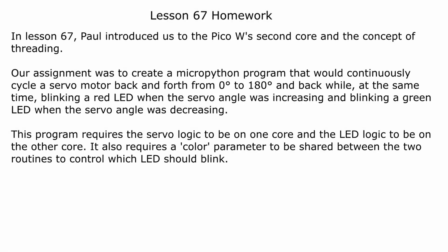In Lesson 67, Paul introduced us to the Pico W's second core and the concept of threading. Our assignment was to create a MicroPython program that would continuously cycle a servo motor back and forth from 0 to 180 degrees and back, while at the same time blinking a red LED when the servo angle was increasing and blinking a green LED when the servo angle was decreasing.